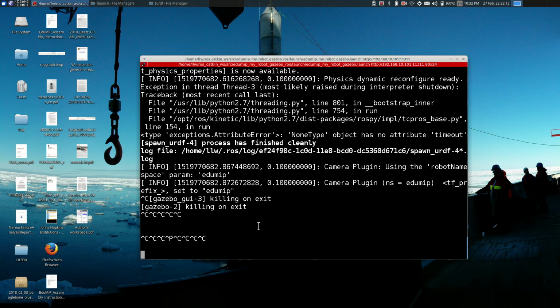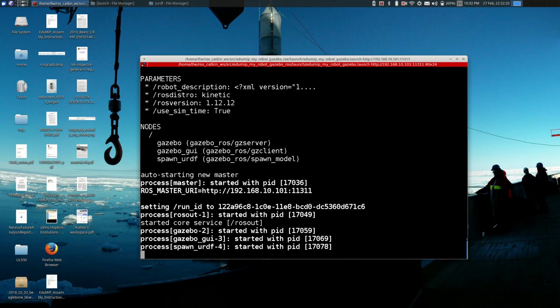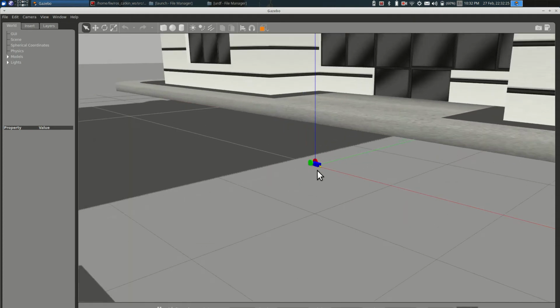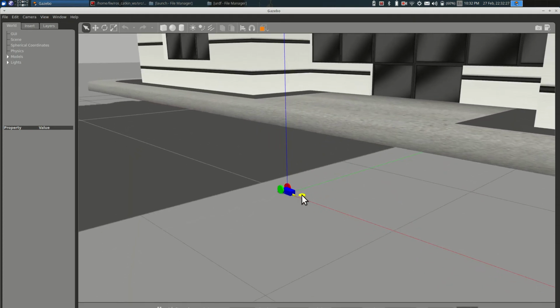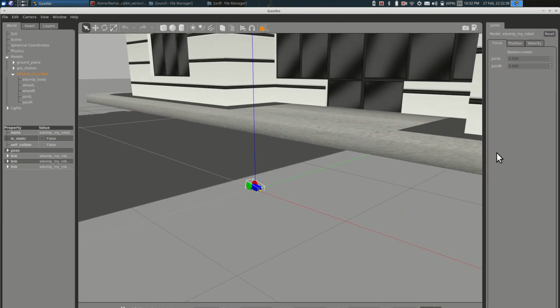It eventually will come back, but sometimes, there we go. There's one more thing I wanted to demonstrate for you here. So the robot's already fallen down on its face. We can select the robot, and there's an invisible button on this monitor, but on other monitors you can see it for pulling out this right-hand thing. When I deselect my robot, I won't get anything here, but I've selected my robot so I can set the positions or velocities or force on joints.